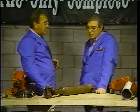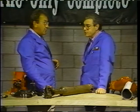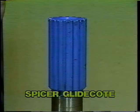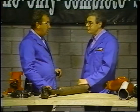So if I use the glide coat, do I still need to lube the splines? Absolutely. Glide coat doesn't take the place of lube. It eliminates metal-to-metal contact and reduces slip forces. Okay, have we covered everything now, Tom? Not quite.